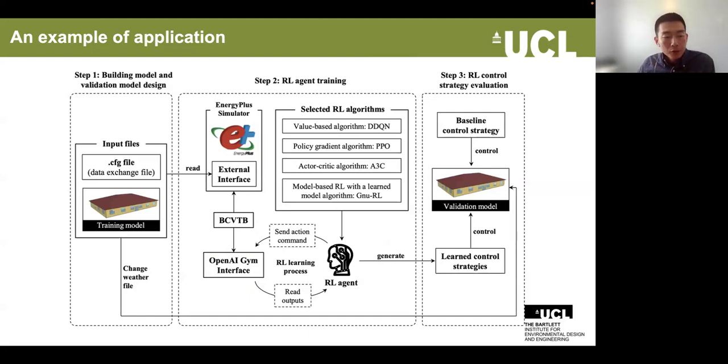In this module, when we introduce reinforcement learning, this is one example I picked from the module. We have the testing platform, and also we have the model on the application of reinforcement learning in building controls. So this figure just gives you a sense of what this testing process looks like. In this case, we use an office building with one story and five zones. We apply a reinforcement learning based control method to control the operation of the HVAC, heating, ventilation, and air conditioning systems in this office building. And we compare the control performance against two other methods, rule-based control and model predictive control.